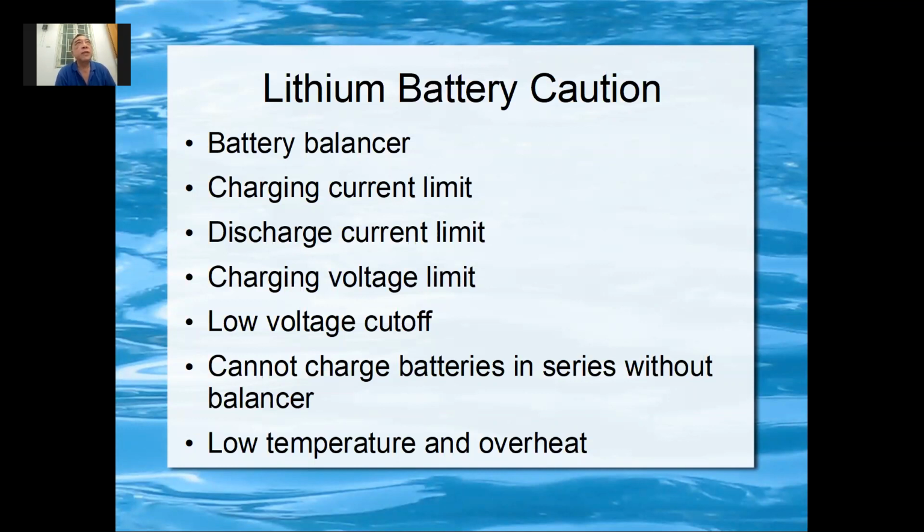Okay, so the other danger is low temperature, which we don't really experience, like winter time. So it's okay. But if you go on a tour, let's say you go to Korea, go skiing, and you left your battery in the snow, then you pick it up, it won't work already. You must warm it up, then it can work. Okay, then the biggest danger is overheat. If you overheat, you can catch fire.